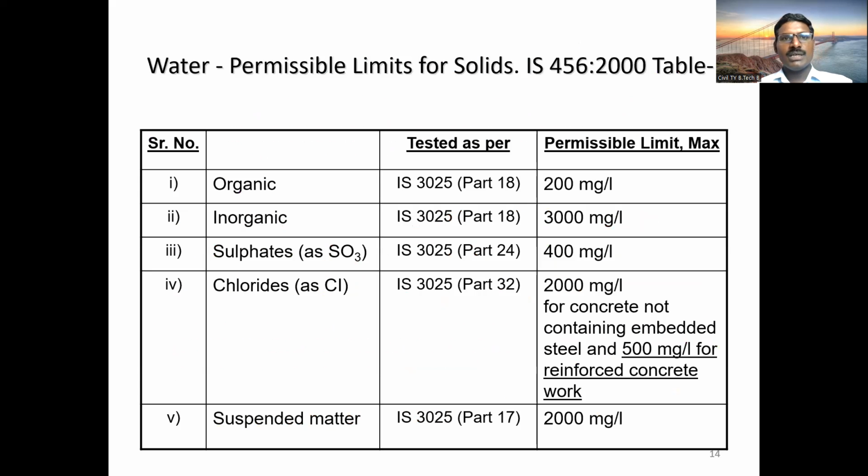So this is the water permissible limit for solids. If organic or inorganic matter, sulfate, chloride and suspended matter are present, they are tested as per this particular IS code, and the permissible limits for the water we are adding are these.